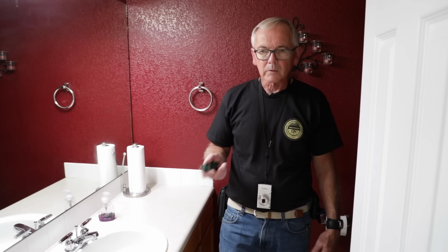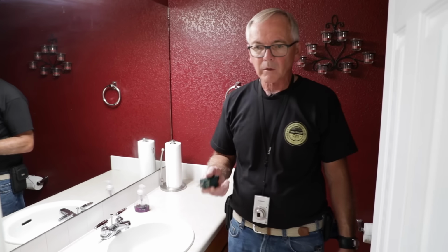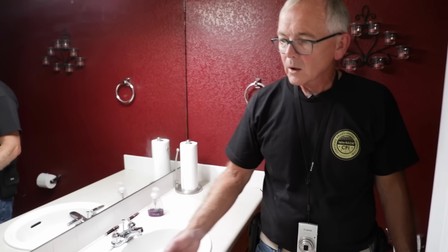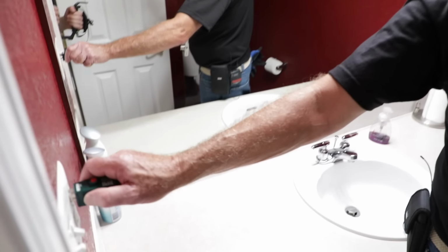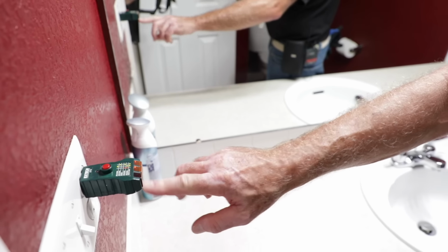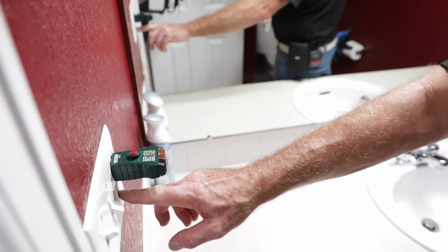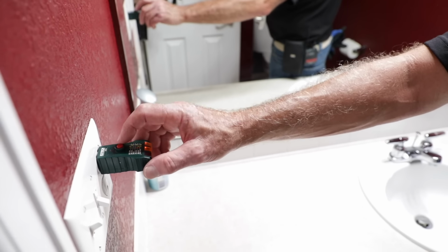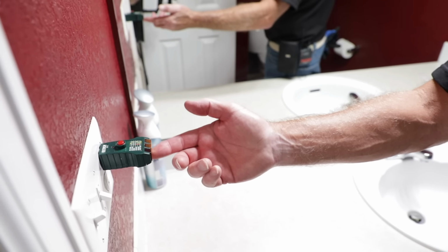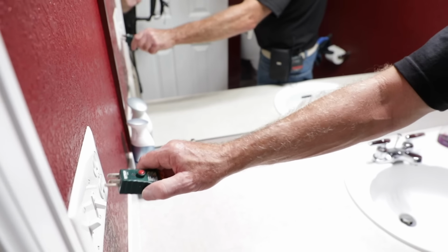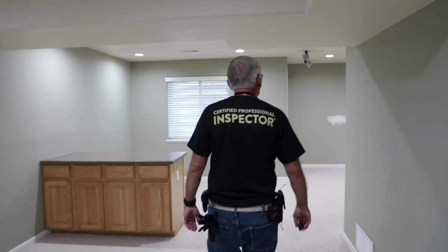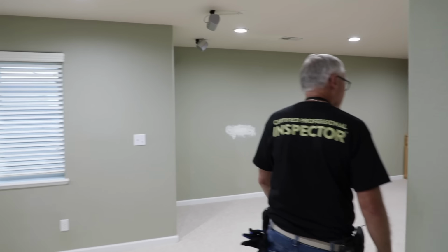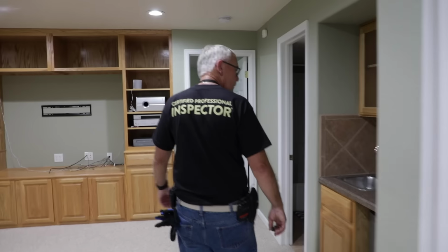We're still working on our ground fault circuit interrupters for the bathrooms, the garage and the exterior. I'm here on the main floor in the half bath. This is a normal receptacle. It is polarized correctly, but in order to assure that this is on a GFCI, I still have to do the test button, and it kicked it off. So somewhere it's being fed by a GFCI, and we just need to find that so we can reset it. So we'll continue on and go down to the basement, take a look at that bathroom and see if that's where our GFCI is.